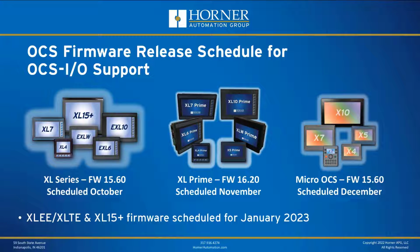Thank you for that. What is the temperature range on the analog input for PT temperature sensors? They are full range for both PT100 and PT1000, I believe. PT100, I know that's like minus 200 to plus 850, but like you said, it's full range. Whatever full range is, it supports full range. Yep, that's a good question.